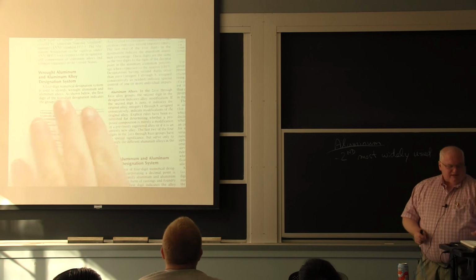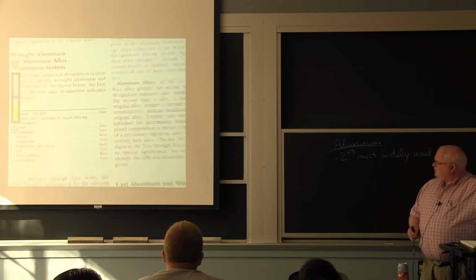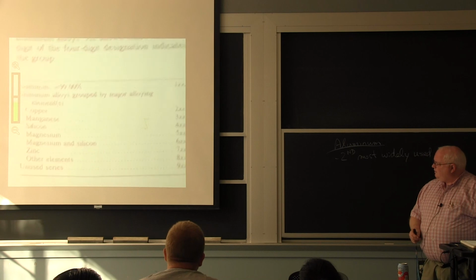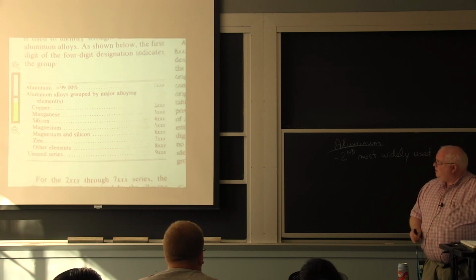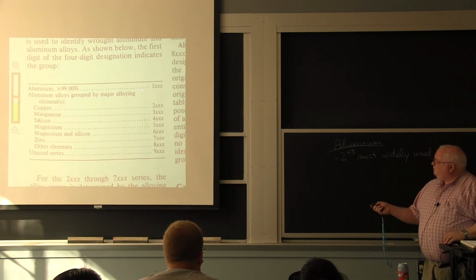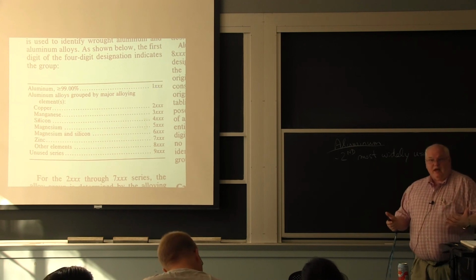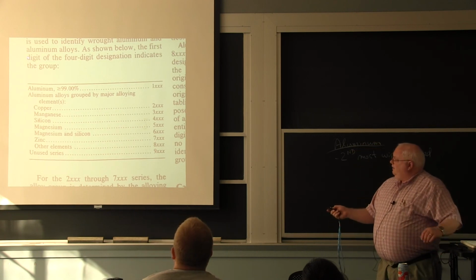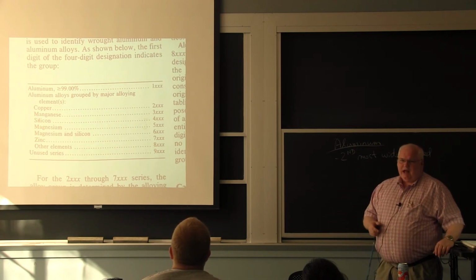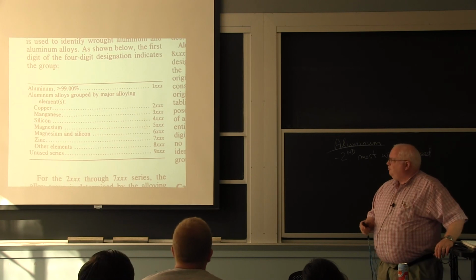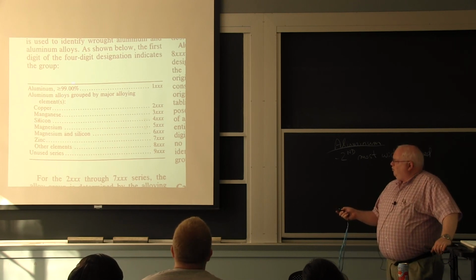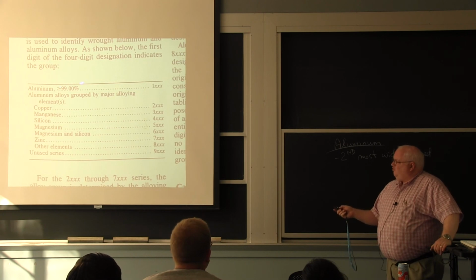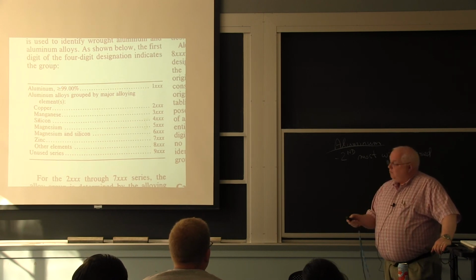The aluminum alloy system for the Aluminum Association is there are, oops, a little too much, 1000 series aluminum. If you have aluminum 1000 alloy, it's 99% aluminum, essentially pure aluminum. I think 1060 alloy is 99.6% aluminum or something like that, or 99.4, I can't remember. You can get up to 4 nines aluminum commercially. Problem is these 1000 series alloys, they don't have strengths better than about 6 or 8 KSI.